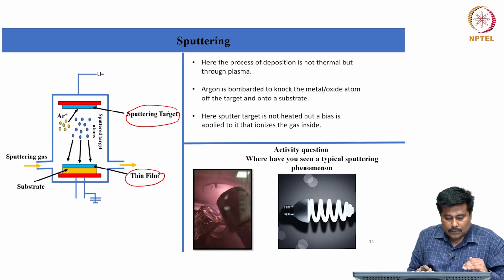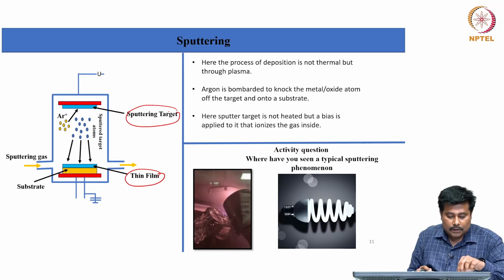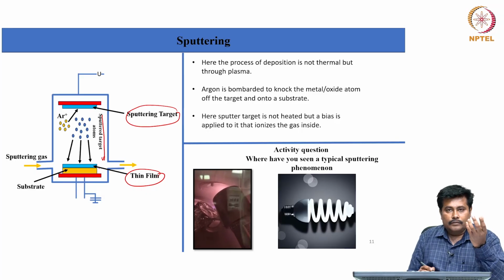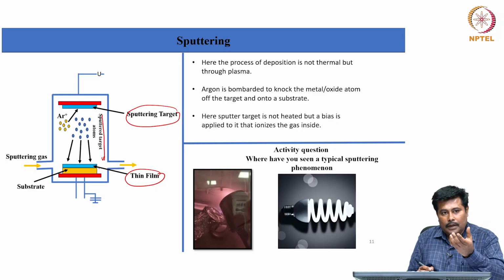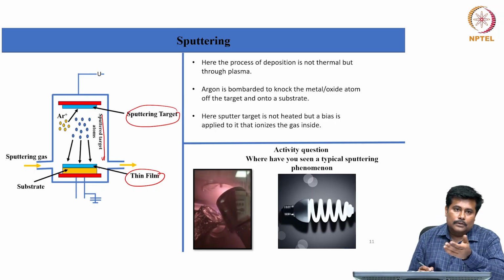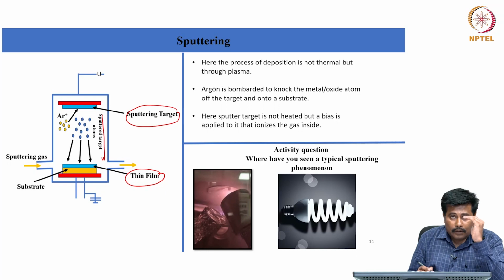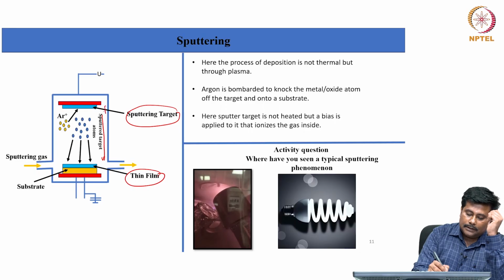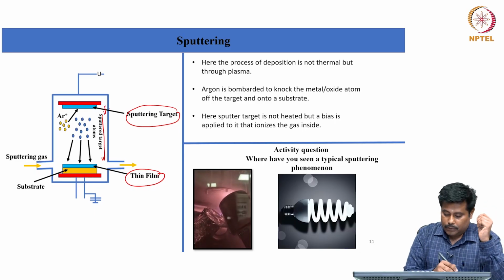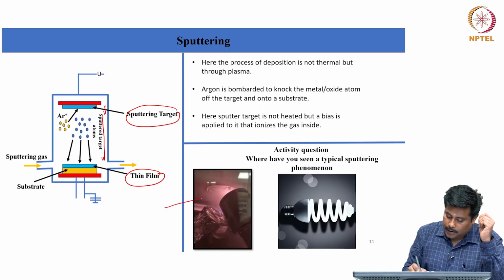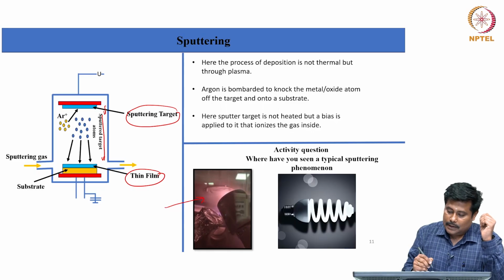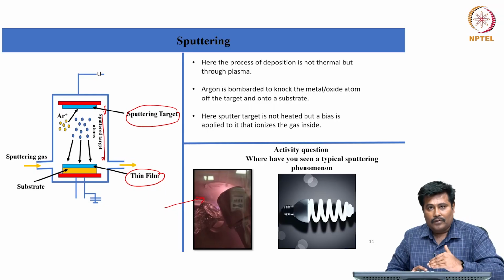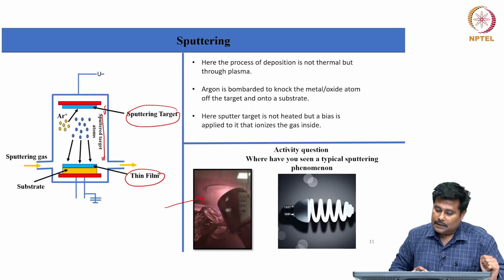Through this sputtering gas, this is the material which needs to be deposited on the substrate. Let us consider that we are developing shape memory alloy based micro robots, where we take nickel titanium as our target. This nickel titanium is sputtered by applying a potential to it, and by applying this potential we get plasma, which sputters on the surface in the form of a thin film, and this thin film will result in a deposition.